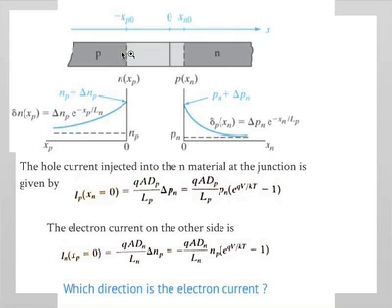And it's a constant injection such that this carrier profile is maintained. Right here is what's important, because the concentration here is maintained at some number, Np plus delta Np. Np is the base concentration without the injection, the concentration of electrons in the p-type material. Then you have the extra injection, which comes from delta Np. Because of the extra injection, you get a concentration gradient, so it will diffuse. You solve the diffusion equation, which gives you this kind of profile based on the diffusion length, which is shown here.